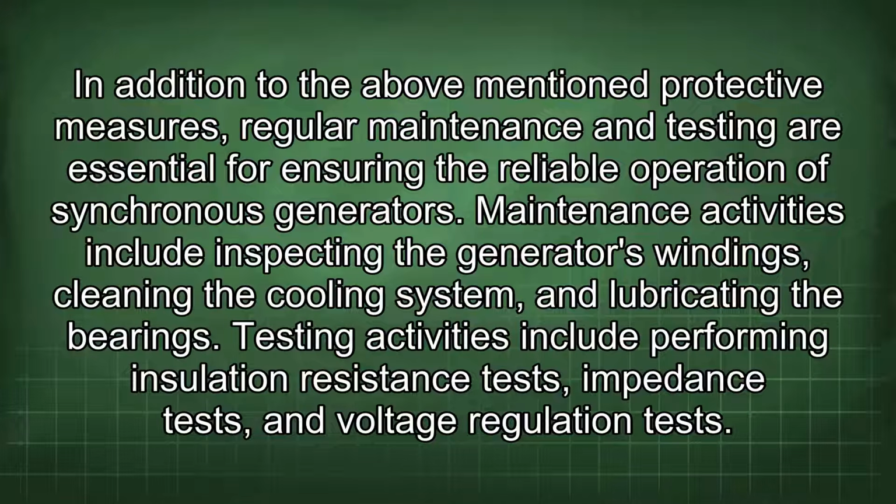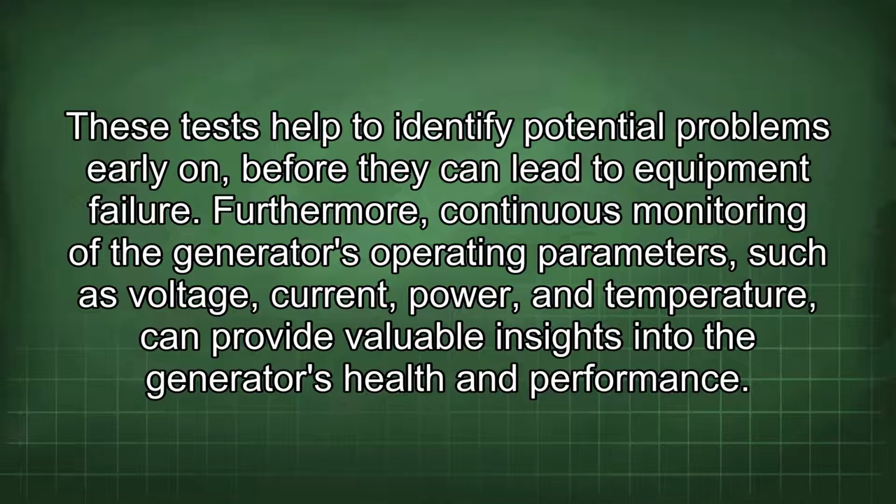In addition to the above-mentioned protective measures, regular maintenance and testing are essential for ensuring the reliable operation of synchronous generators. Maintenance activities include inspecting the generator's windings, cleaning the cooling system, and lubricating the bearings. Testing activities include performing insulation resistance tests, impedance tests, and voltage regulation tests. These tests help to identify potential problems early on before they can lead to equipment failure.